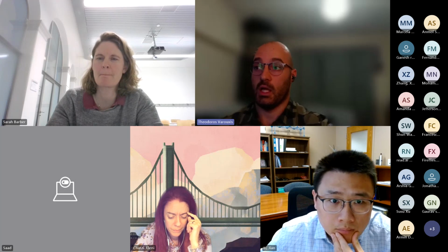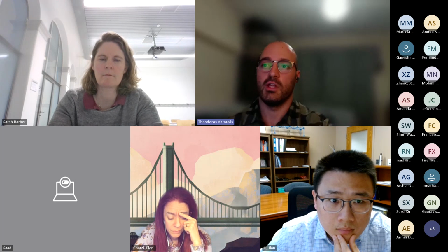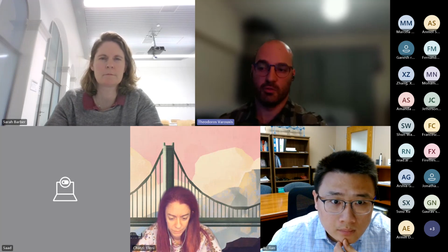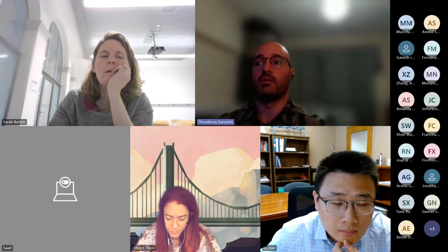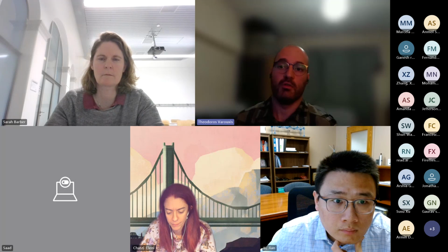What I would try to do coming from this was to try and use only the accelerometer used for the pitch drive failure and see whether we can use this one sensor channel to initially do damage detection, so another binary classification for all damage cases, and then try and see whether you can do damage classification or damage identification. But at the moment, because there were only a few test cases where more than one type of damage were present at the same time, we only focus on damage detection.